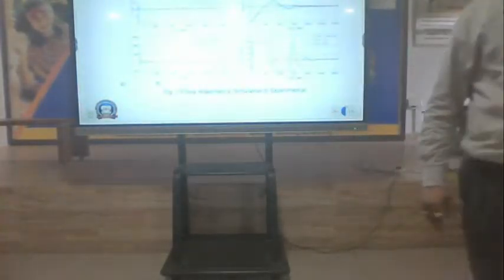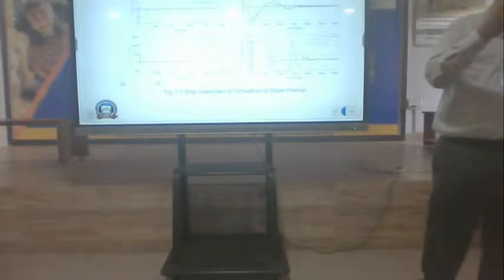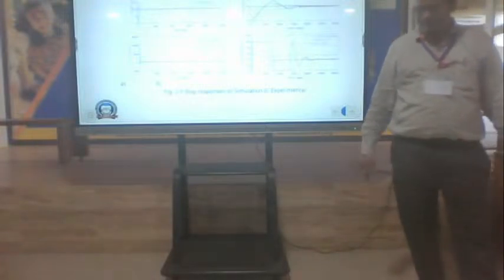You can extend this for electrical vehicles, like the speed. Let us say I am giving a reference speed of 1500 RPM. If we are using reference one, the speed is going beyond 1500. If I take the proposed controller, it does not exceed the reference value much; the peak value increment beyond the reference value is small. That's why our higher order filter is good.